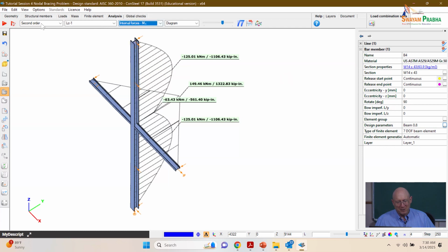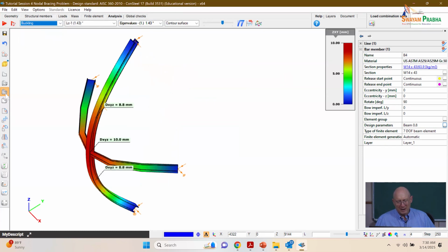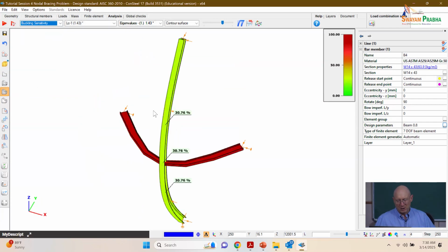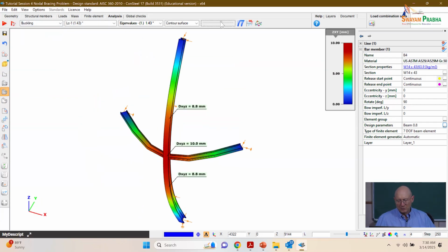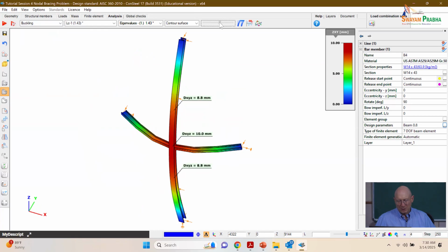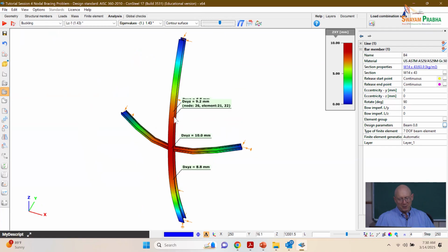If we go to buckling analysis. So our buckling analysis here, let me turn this so that's, okay. Yeah, so it's actually buckling toward us. We'll tone down the buckling mode there a little bit. Yeah, so the first buckling mode is kind of what we're seeing here with the partial brace, right? We would expect to be getting some of the largest amplification of the displacements based on the way we put this bow in the column.